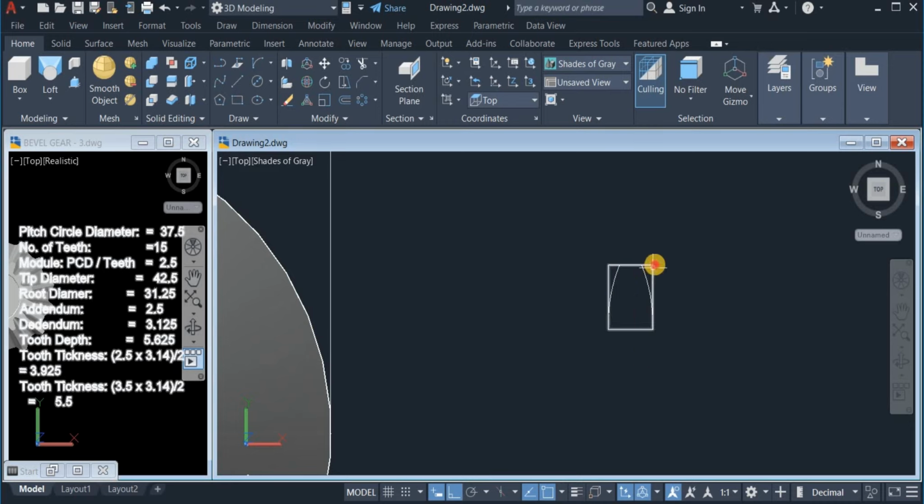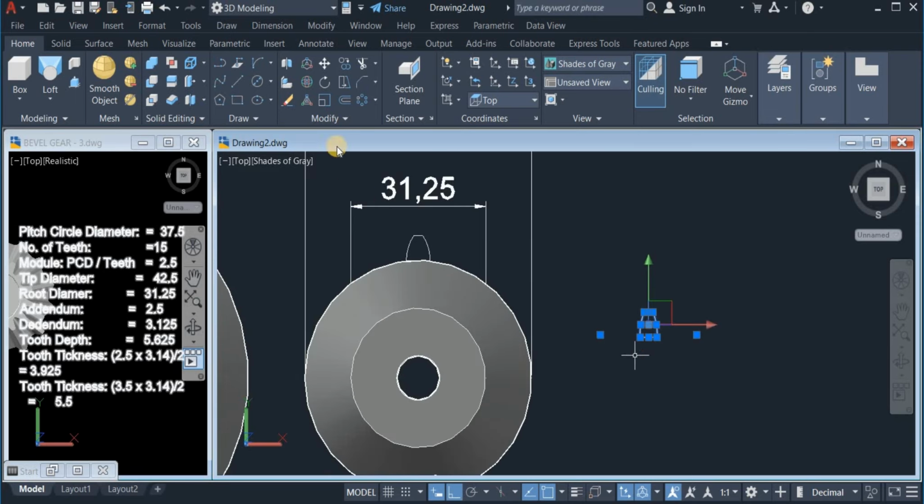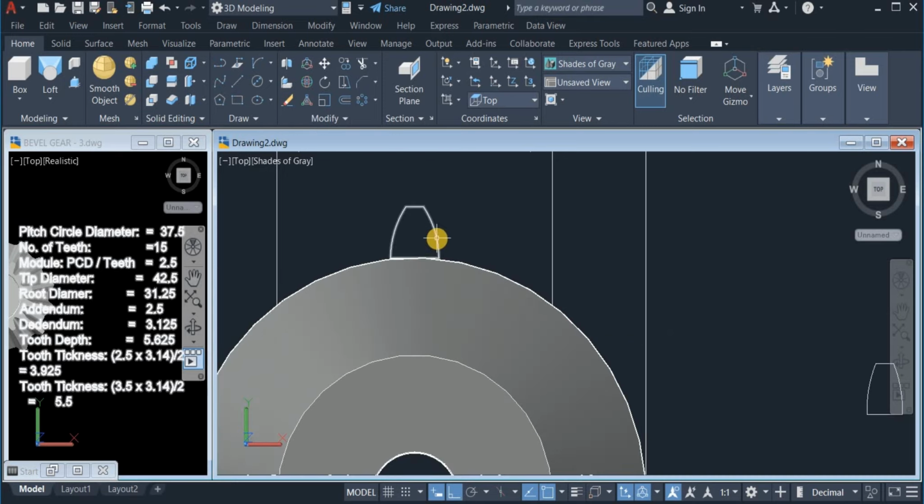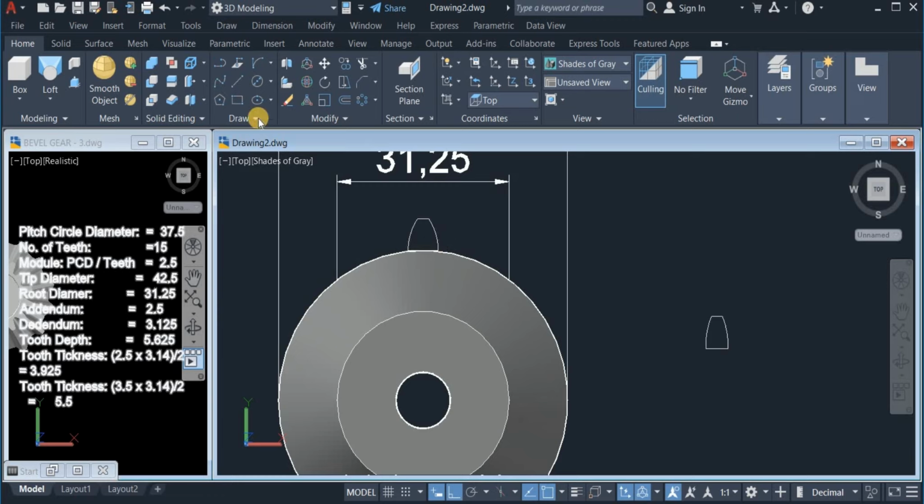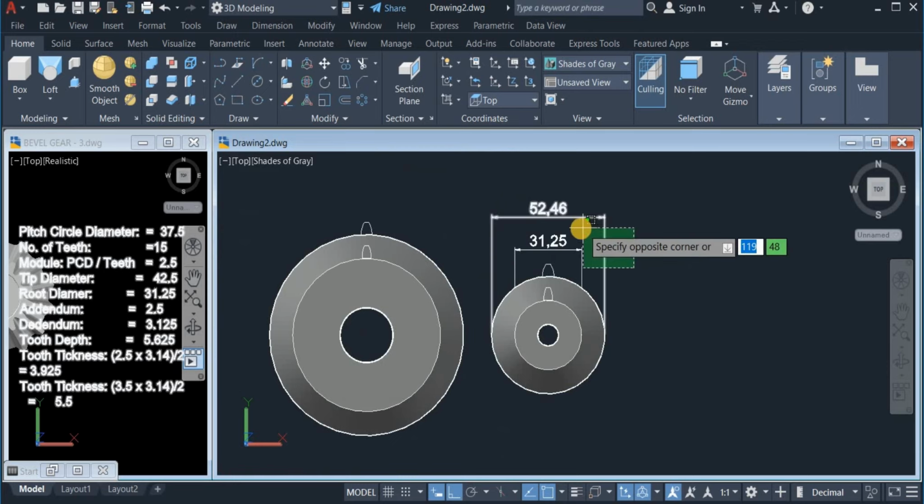Okay, now remove this and close up again. Click on line command and close this up. Alright, join it up. And you can join. Okay, so move this again. Move this from this point and drop it at the quadrant point of this. Alright, so I can now clean all these ones as well.